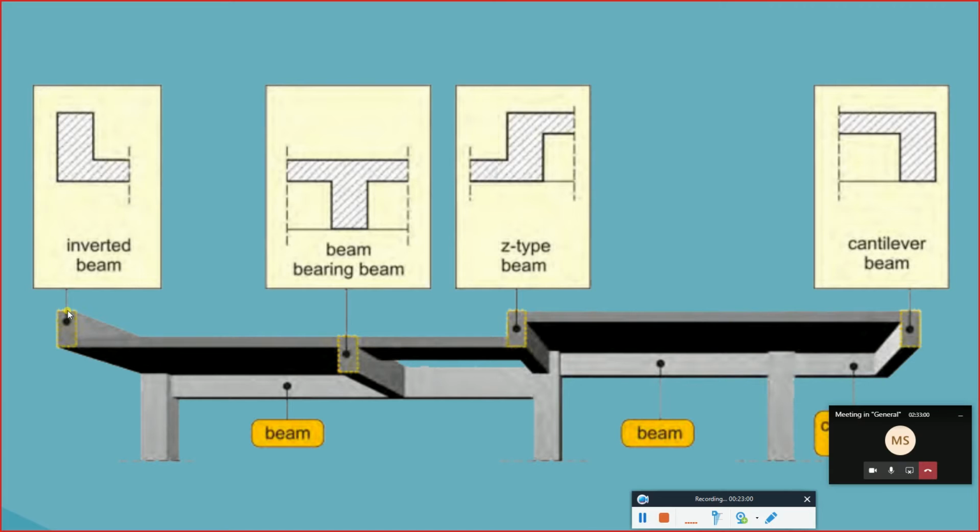Another thing, instead of using a parapet wall, which is used at the roof, I want to use concrete. For example, the height of that parapet wall was a bit huge. If we keep a regular block, it will be affected by the wind or lateral loading. So I want to go for concrete. If I go for concrete, then my beam is not going to be down; it's going to be up. So it's going to be an inverted beam.